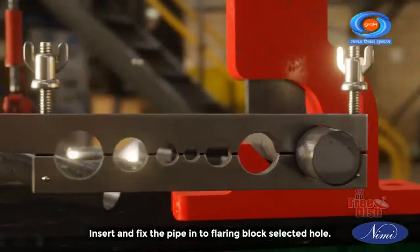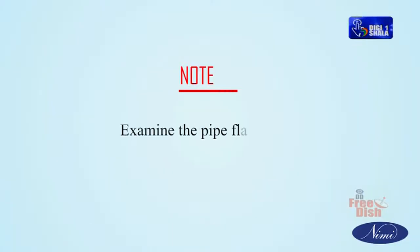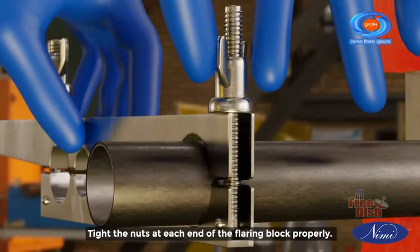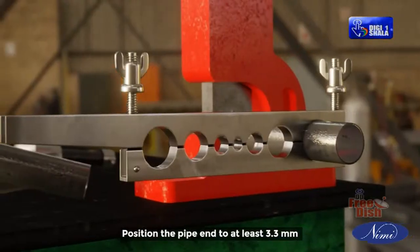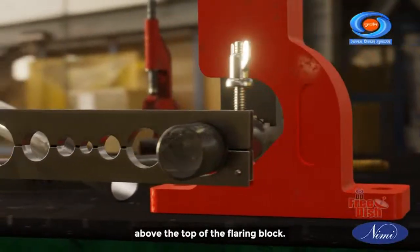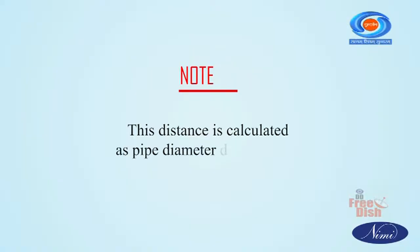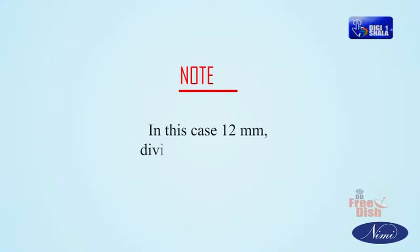Insert and fix the pipe into the flaring block's selected hole. Note: examine the pipe flaring tool before starting to flare the end of a pipe. Tighten the nuts at each end of the flaring block properly. Position the pipe end at least 3.3 mm above the top of the flaring block. Note: this distance is calculated as pipe diameter divided by 3, in this case 12 mm divided by 3, which is equal to 4.0 mm.